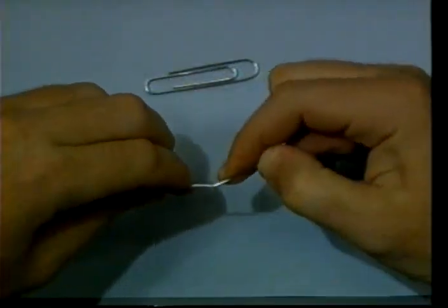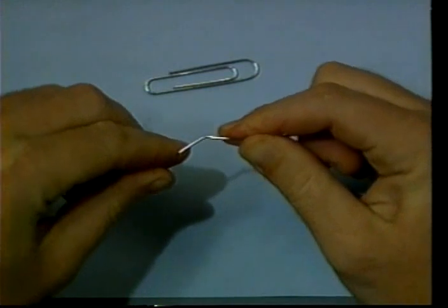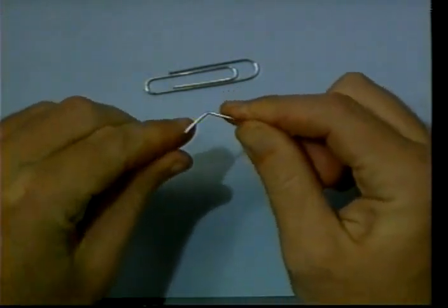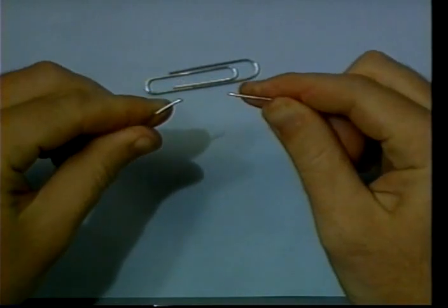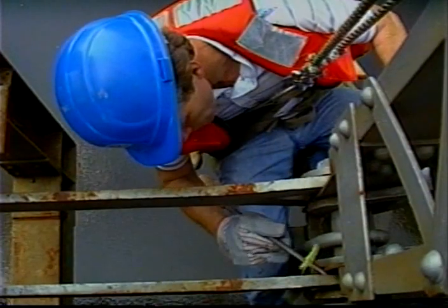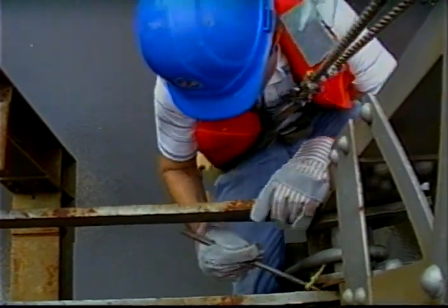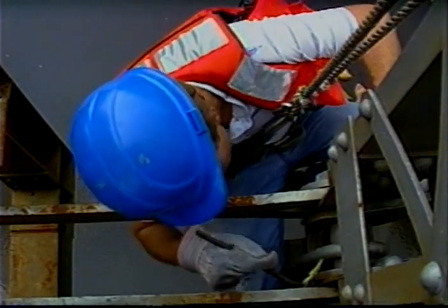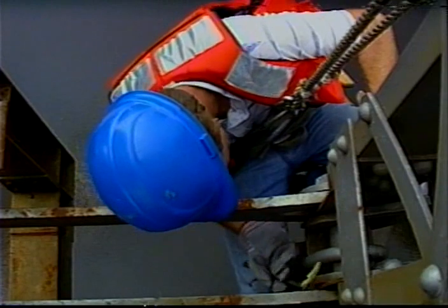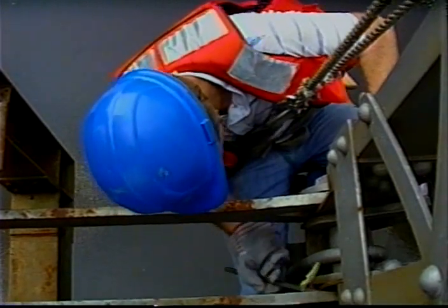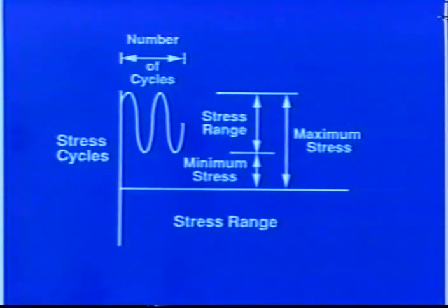Fatigue is similar to the repetitive extreme bending of a paper clip. Each time the steel is stressed, it can cause minute damage to the material until it finally breaks. If overweight trucks use a bridge repeatedly, the components may gradually accumulate internal damage until a failure occurs, perhaps under a relatively low loading. Three factors affect the fatigue life of a bridge.